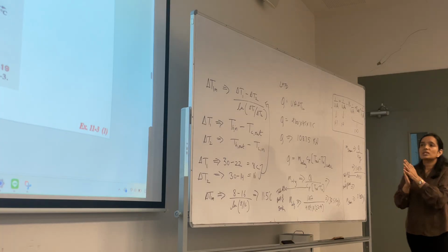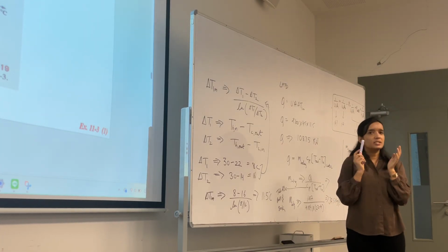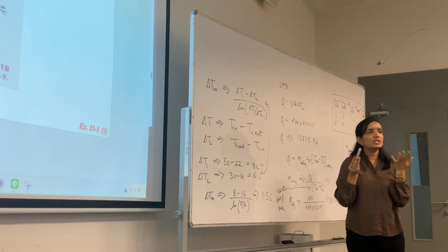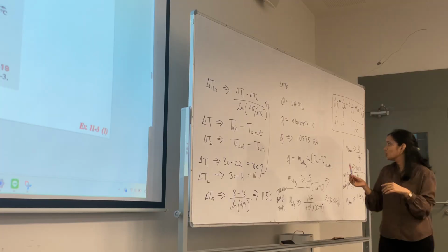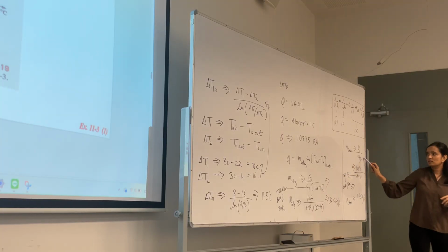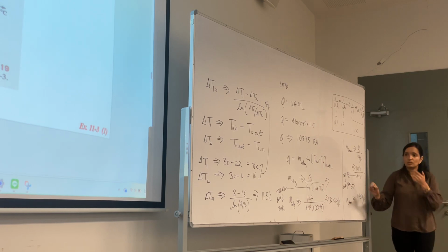So the question was asking mass flow rate for the water and for the steam. Like I'm saying, if you are cooling the steam, steam will change into liquid. There is a phase change. So you use the enthalpy. This value is from the back of your book. If I'm giving you this in exam, of course I will provide the value.